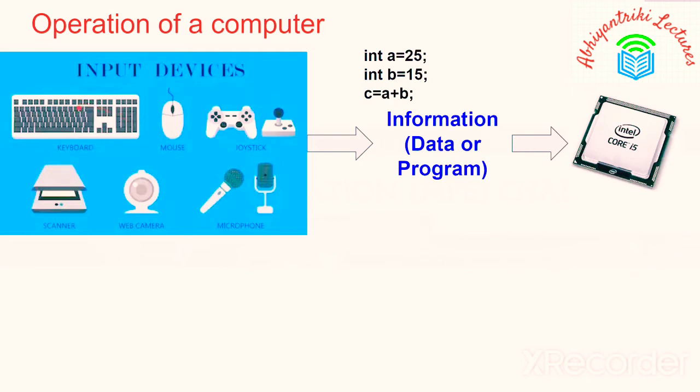Whenever a key is pressed from the keyboard, the ASCII value of the pressed key will be stored in the buffer register. A buffer register is a memory storage element. It stores the data. Whatever characters you enter will be converted to ASCII value and stored in the buffer register. Why are we using buffer registers? They are placed in the input as well as output devices.